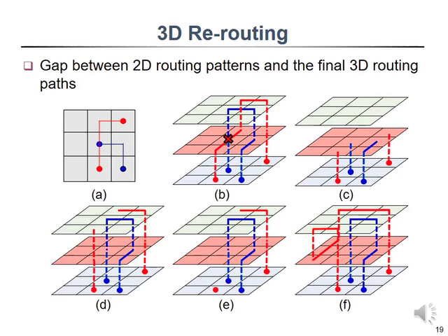In this layer assignment instance, our concurrent layer assignment will also cause an overflow, and thus one segment of the red net is not assigned. For the red net, we will remove those redundant segments and vias as shown in Figure E, and perform 3D rerouting, and the result is shown in Figure F.